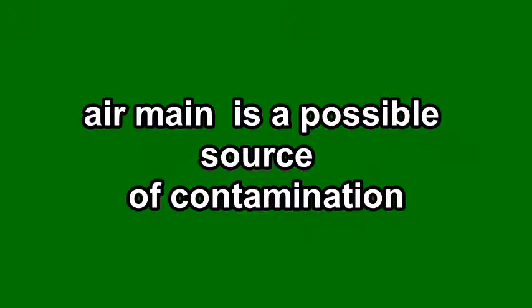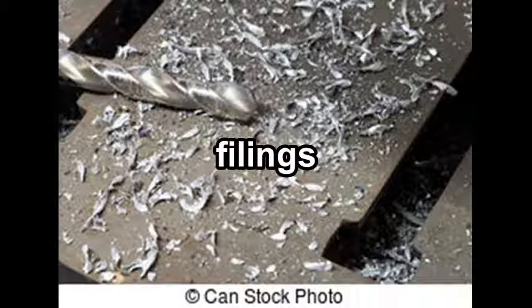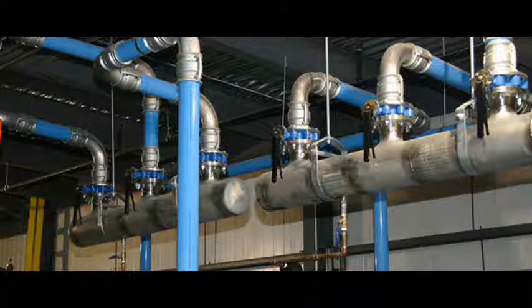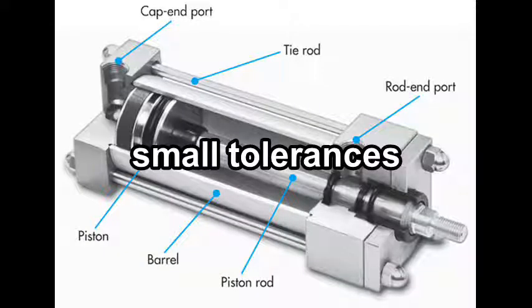The air main can be a tremendous source of contamination in the installation process and during everyday use. During the installation process, care must be taken to reduce the metal filings, pipe dope, and other foreign materials that will be generated from assembly. The large size of most air mains makes contamination seem acceptable. Yet when the contamination is seen relative to the extremely small tolerances in modern automation components, such as valves and actuators, the effect can be disastrous.